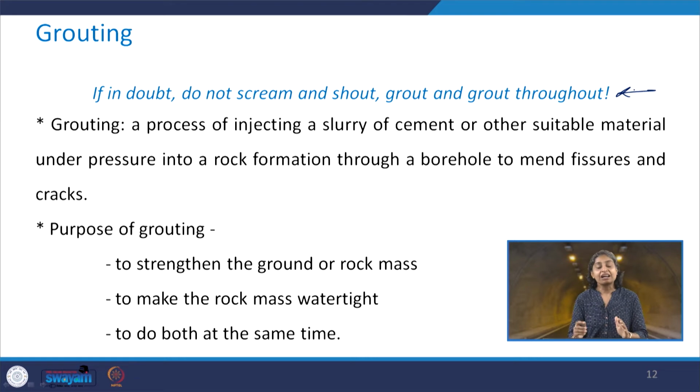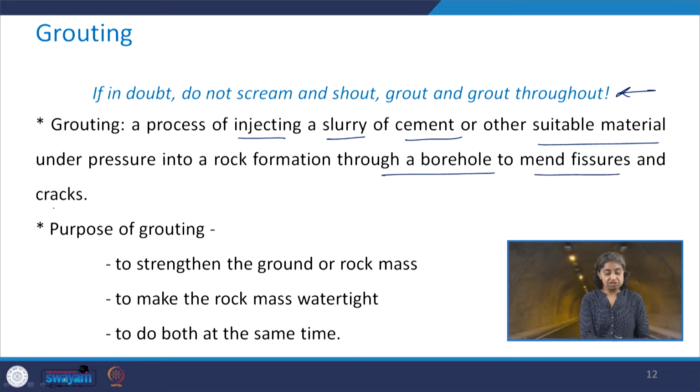So what exactly do we mean by the term grouting? This is a process of injecting a slurry of cement or other suitable material under pressure into a rock formation through a borehole to mend the fissures and the cracks. When we go for grouting, first we need to have the borehole and then we inject this grouting slurry under pressure into that rock formation.